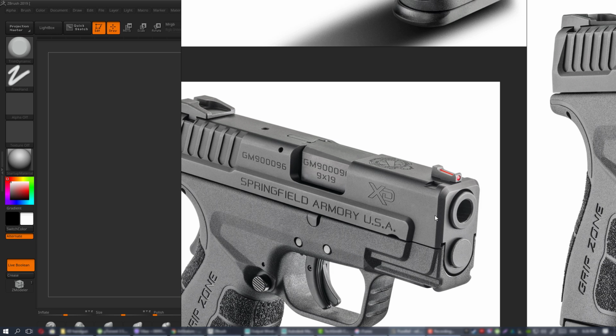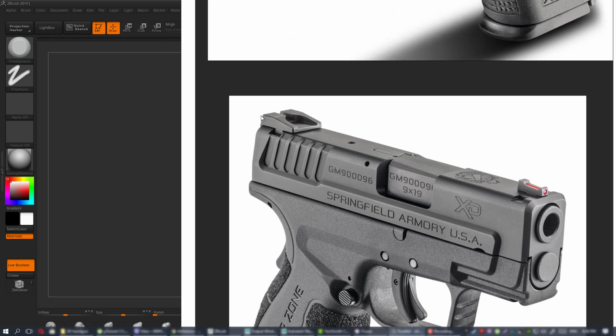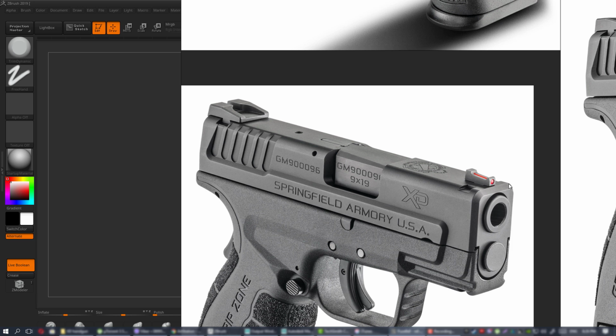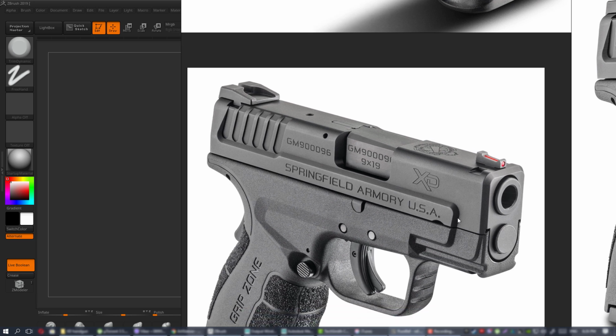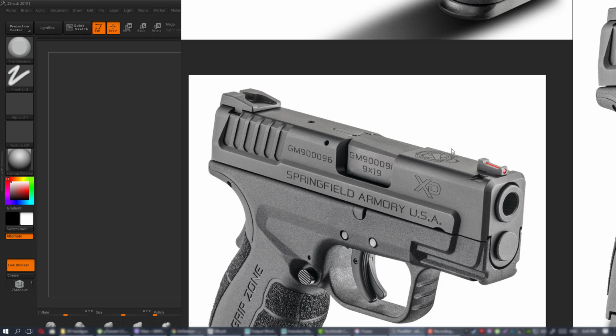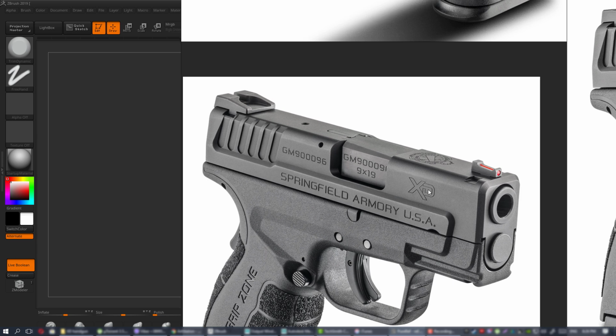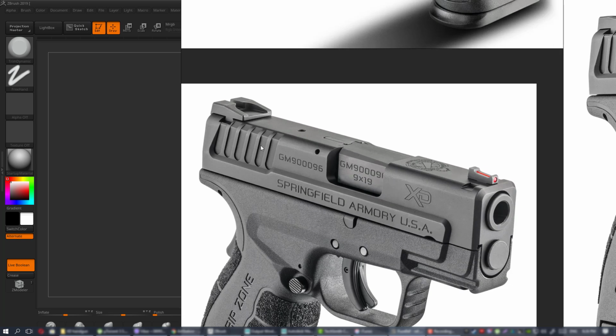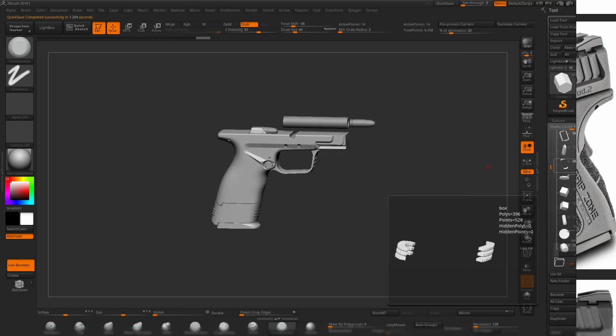First part is going to be this boxy shape that will go all the way along the whole length of the frame, and the second shape is going to be similar but wider, which will represent this shape. What I'm going to do is just duplicate this one, scale it sideways so that it will be as wide as this thing, and then I will just cut off this shape. So I guess this is the most logical way in my situation how to do this.